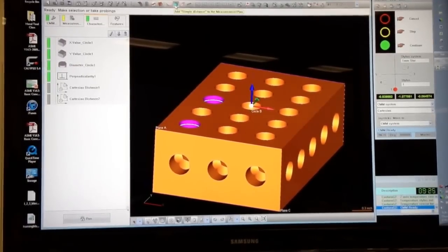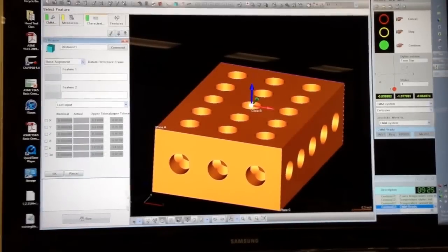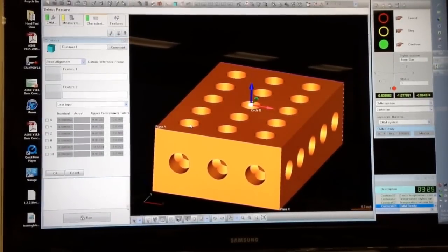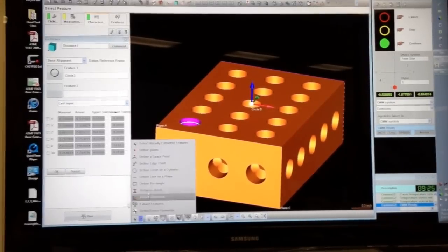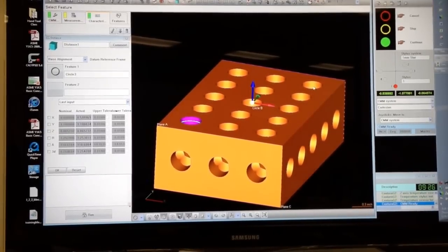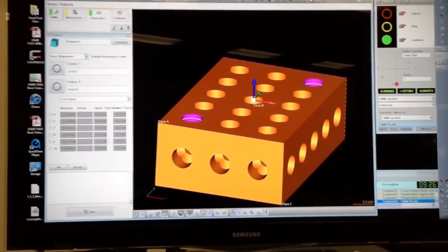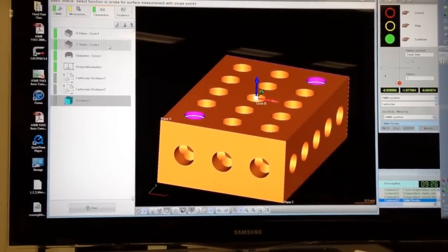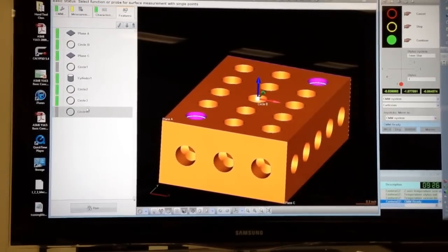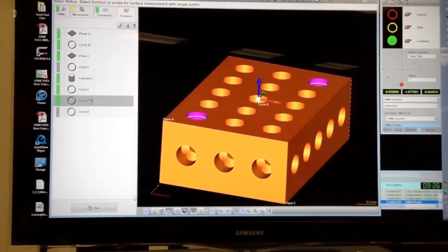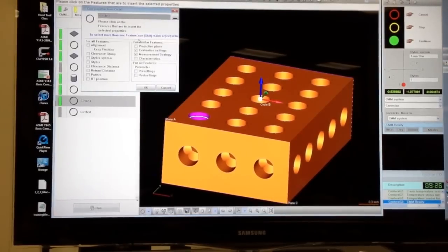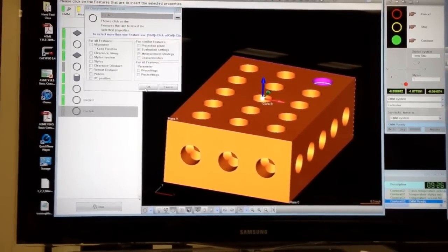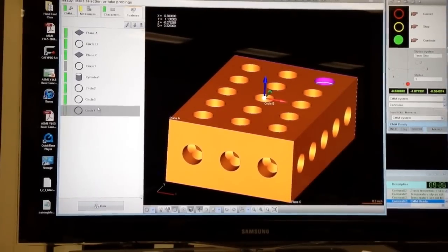So once again, I can start with the simple distance. I'll open that up. I have the Select Already Extracted Features tool already active, and so I can simply get this one here. Next, I switch to Define a Circle on a Cylinder, get the opposite corner, and of course I want to know the x and y distances between these elements. Once again, I can get the settings for circle 4 by going to one of my previously set circles, go to the Format Painter. You'll see the checkboxes I'm using are still highlighted from before, so I simply highlight circle 4, click OK, and now the settings have also been applied there.